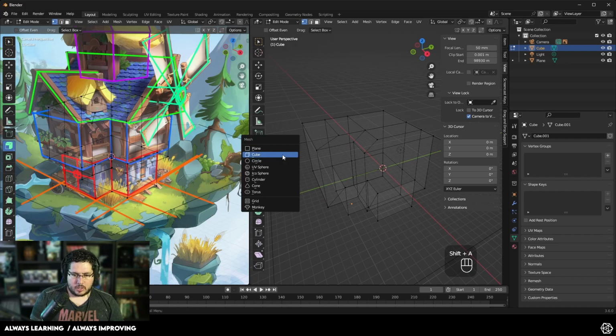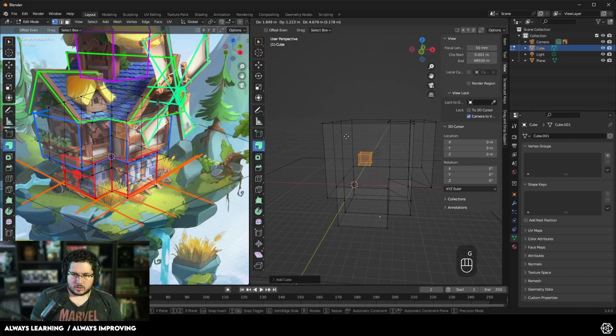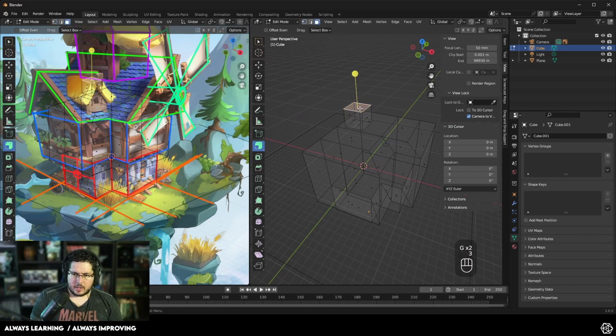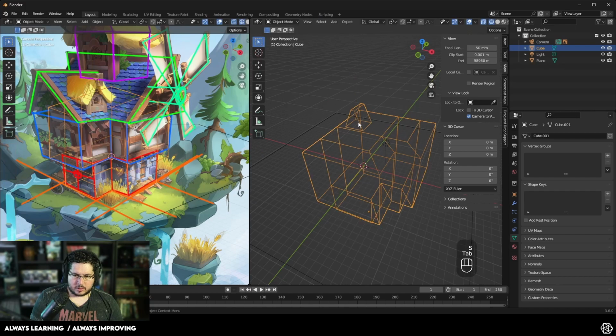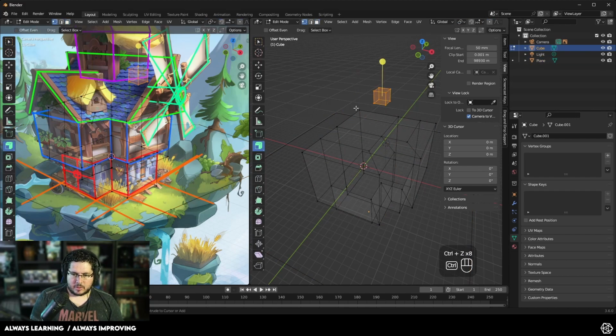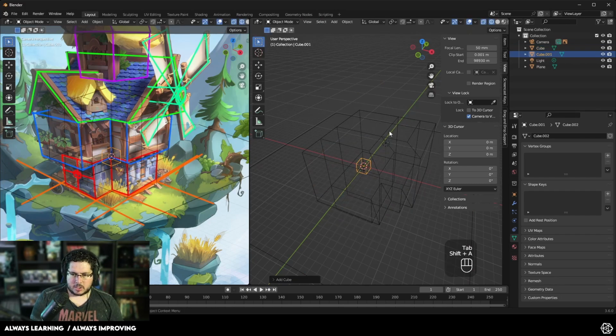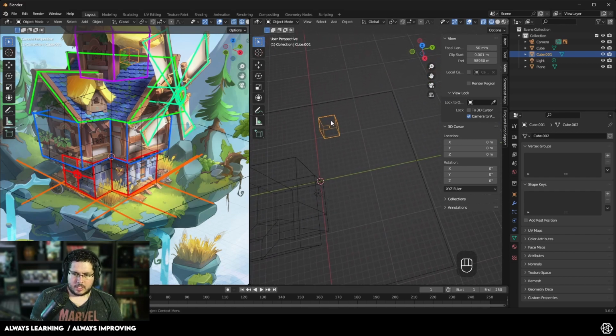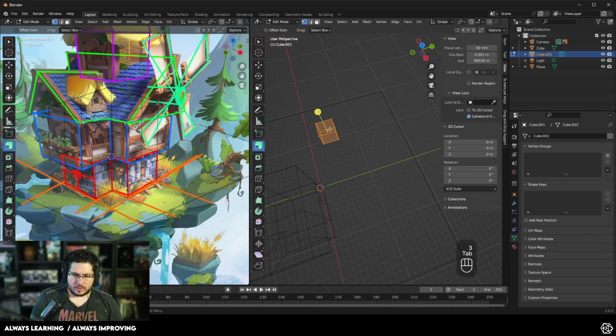In this case, I'm just going to do another cube. It's going to be a lot easier to just do another cube. Bring this cube to the front. Grab this face. Scale on X to make this face a lot smaller. Oh, I hate when that happens. Let me go back. Let's go out. Add mesh cube. There we go. And I'm just going to go into component mode.